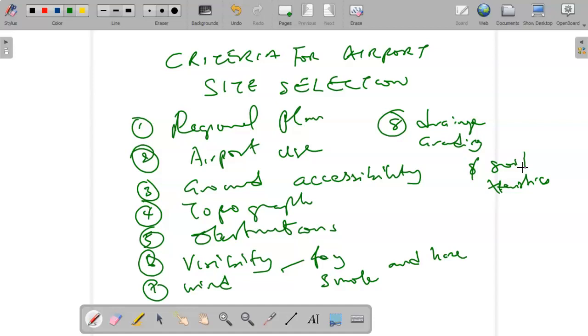The original ground profile of a site, together with any grading operation, determines the shape of an airport area and the general pattern of the drainage system. The possibility of floods at a valley site should be investigated. Sites with a high water table, which may require costly subsoil drainage, should also be avoided.